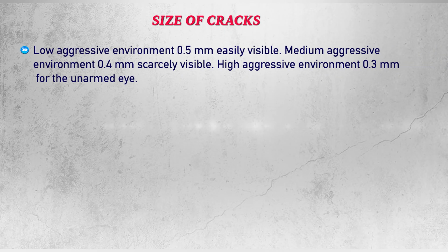Low aggressive environment: 0.5 mm, cracks are easily visible. Medium aggressive environment: 0.4 mm, these are scarcely visible. Then high aggressive environment: 0.3 mm, for the unarmed eye. So these are the criteria for allowable cracks in different environmental conditions.